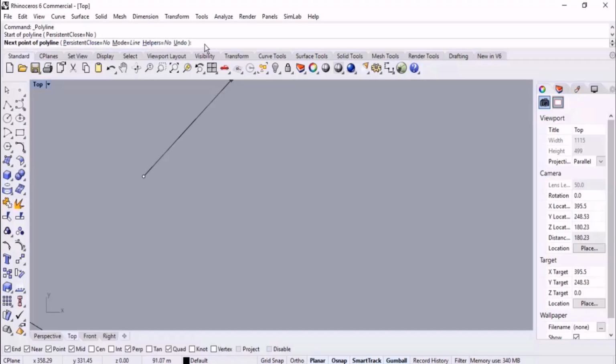I want to draw your attention to the command line. Watch this please. At first, I type the less symbol, and then I specify the degree or angle, 30 degrees for example. But note that when we specify the angle or the degree, for example 30, that 30 degrees angle is not given to us. Right now, the specified angle at which the movement of the cursor is restricted is 30. As you can see, when we rotate it, we got many parts that each of them are 30 degrees. So at first we specify the degree or angle.